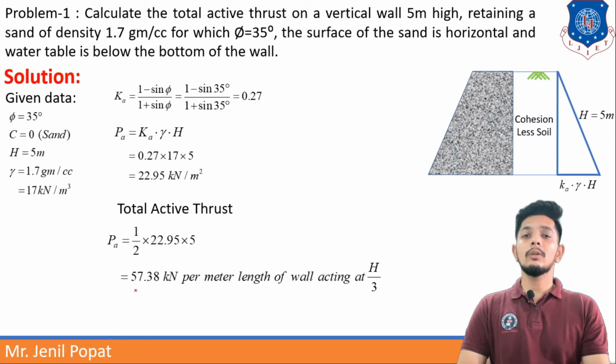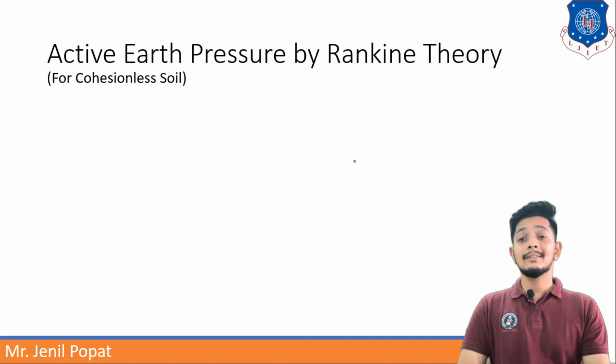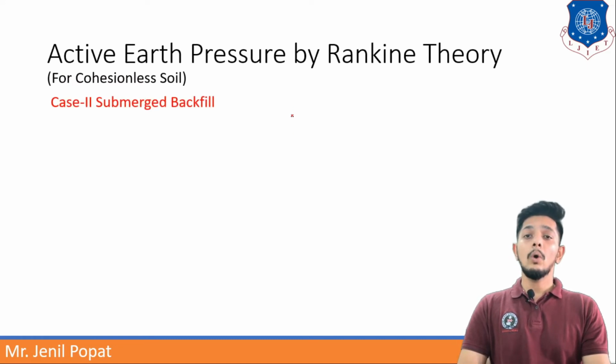Now this is my total force, which will be acting at what height? H by 3. That means 5 by 3 height. So that's it in the first problem. Let us go to the second case given by Rankine. Case 2 of submerged backfill. If the backfill is submerged.